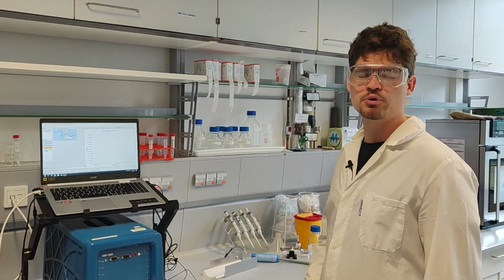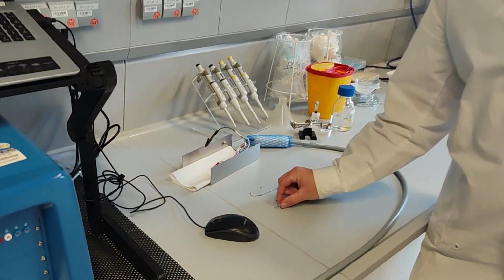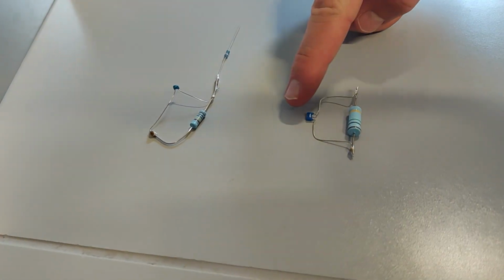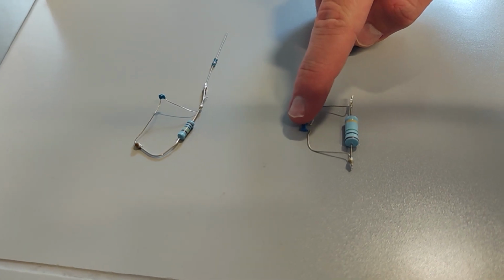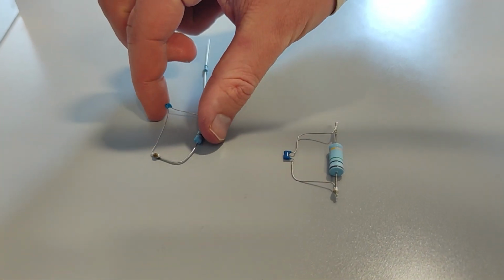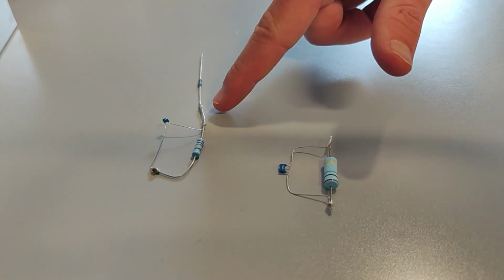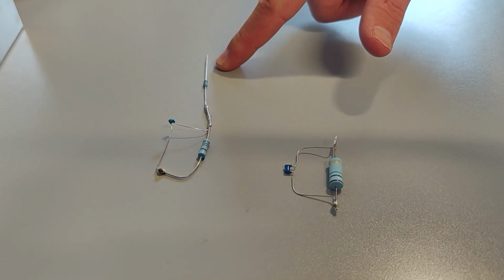Welcome to the lab. Now that we know what we expect from our impedance spectra of an RC parallel circuit with and without a resistor in series, I've built these circuits again here with electronic components, and now we can measure them to see if the spectra match our expectations. First of all, we have here an RC parallel circuit with a 1 mega ohm resistor in parallel with a 10 nanofarad capacitor. And here we have that same 1 mega ohm resistor parallel to 10 nanofarad capacitance in series with a 100 kilo ohm resistor.